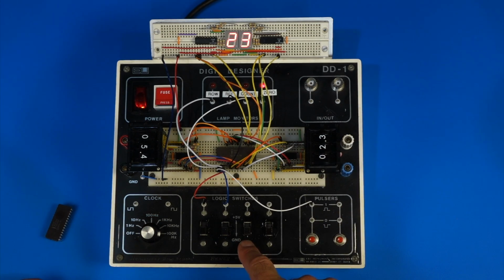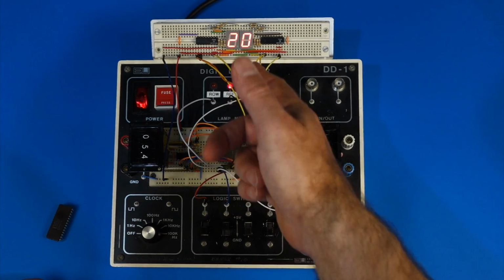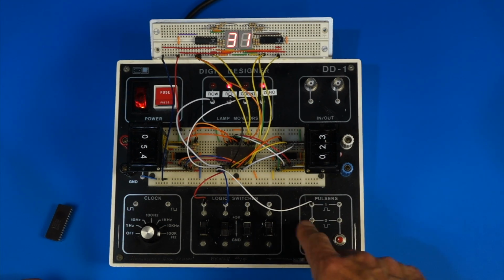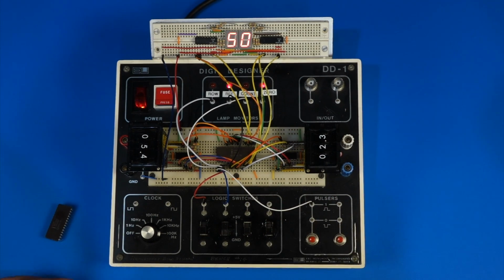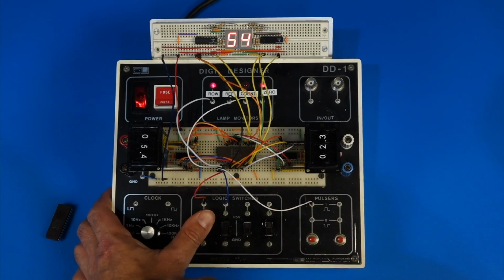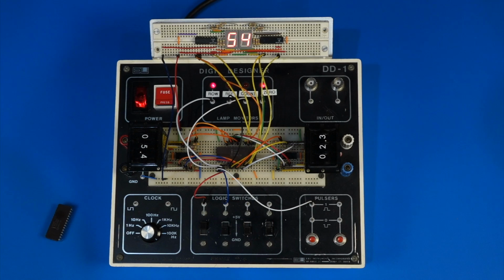And then the next one is just refresh. I just do refresh. And right now the refresh counter is at 20, so if I want to refresh the next row, I give it a count. So it comes from the internal counter in the chip. So it's doing what it should. It just switches between refresh and the row and column inputs, and chooses one out of the 3 ports.